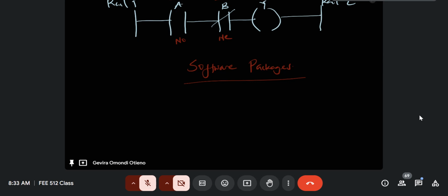And then you can always try and run a few programs on your own at home and check, because usually you have to draw a ladder diagram to represent what you're trying to implement in the PLC. Once you have completed drawing your ladder diagram, you need to compile the program, just like you do with other text-based programs.